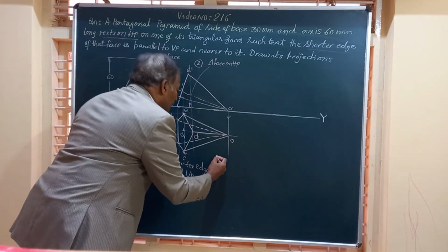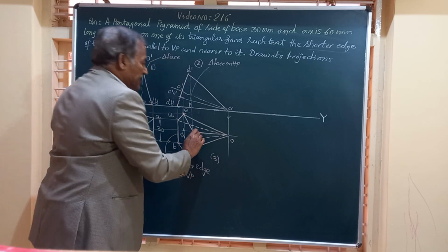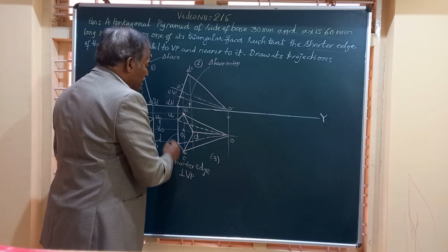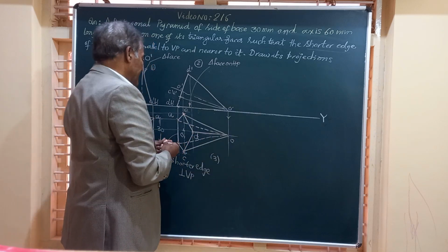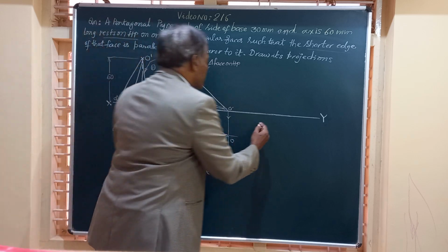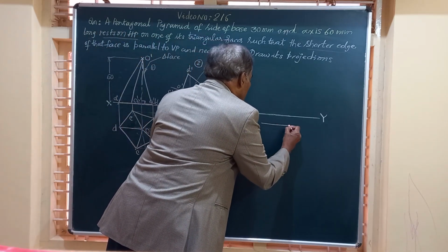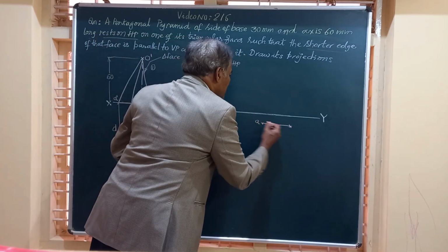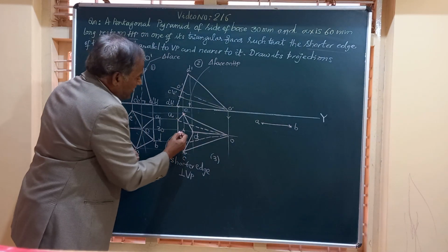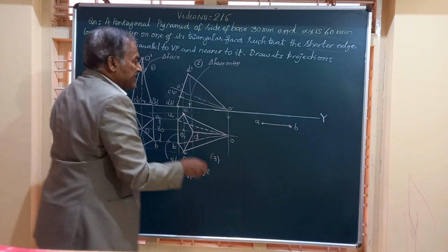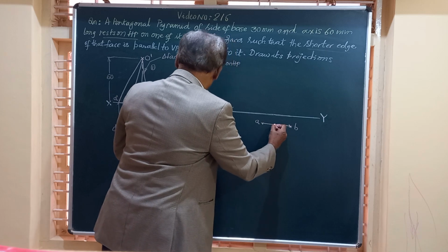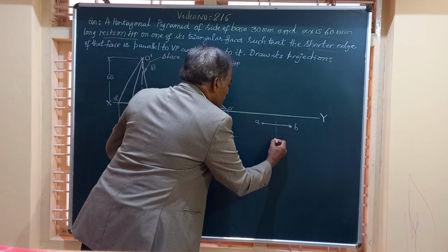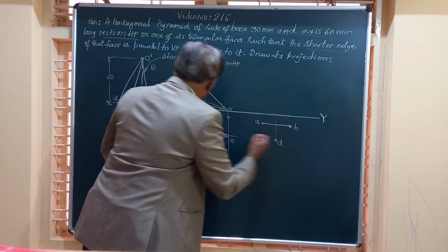That is to say, I have to draw this figure 3 as figure number 4 such that ABCDE, the base, is nearer to the XY line. Friends, it is very easy to complete this. So friends, this is AB, we can just say AB, and then from AB you draw a vertical line and locate the point D. Draw a vertical line, locate D on this. So D is somewhere here. Okay, let us say this is our point D.